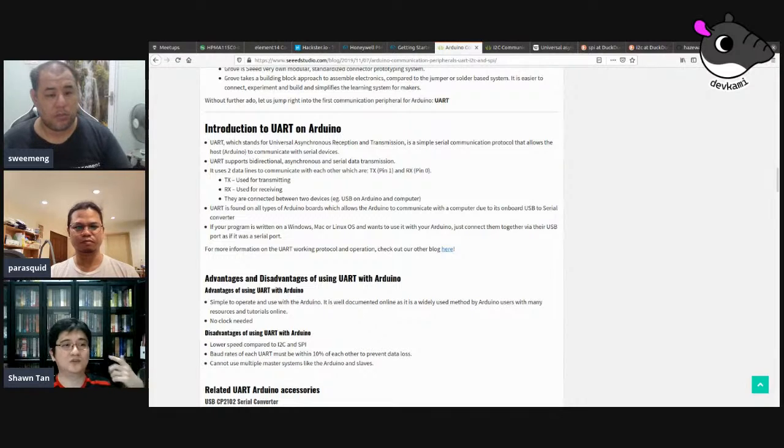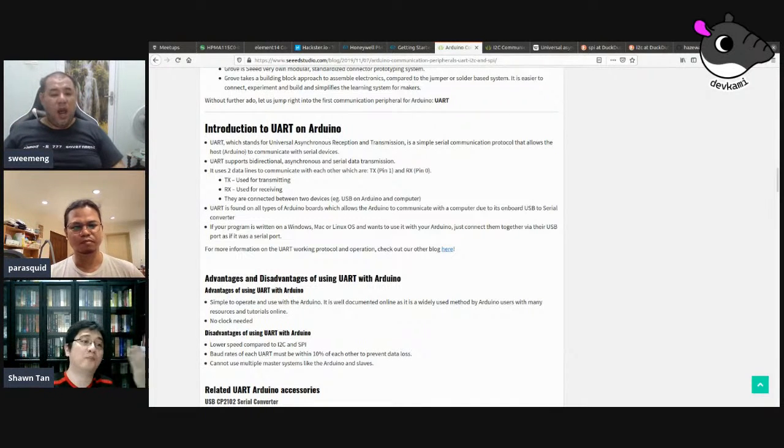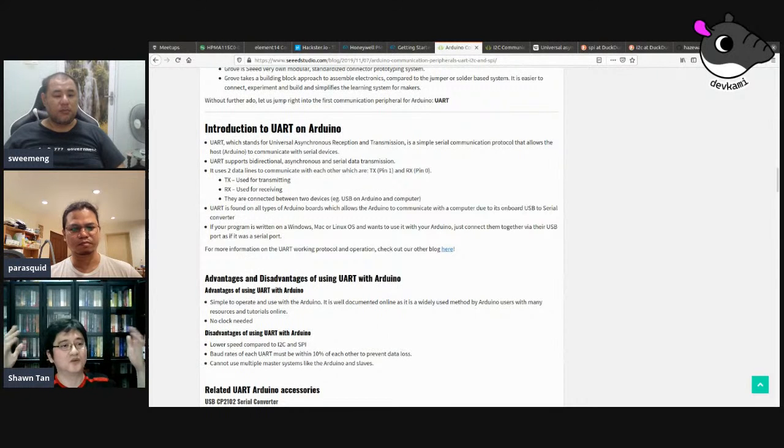And the two devices, unless they are from the same manufacturer, same batch, if they're completely different families, one may be running at, let's say, a 25 megahertz clock. The other one is running at a 24 megahertz clock. And then you divide down with different device values to get the clock down to 9600. But 9600 is a very weird number. Not a nice binary number or something like that. So you have to have some very weird divisor to divide the clock down.